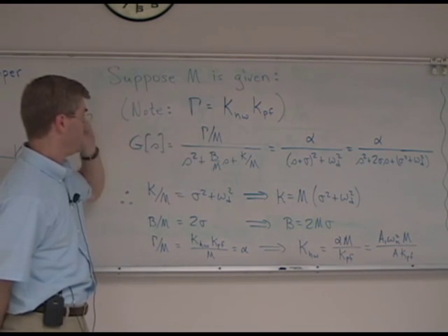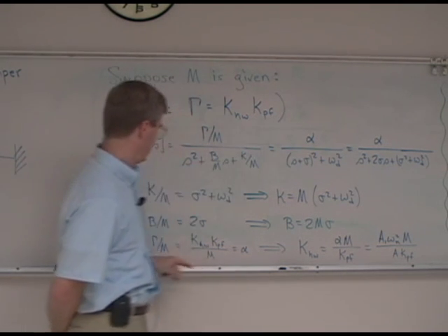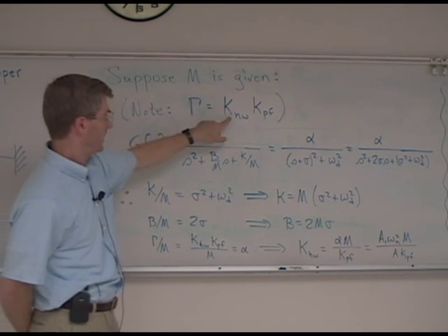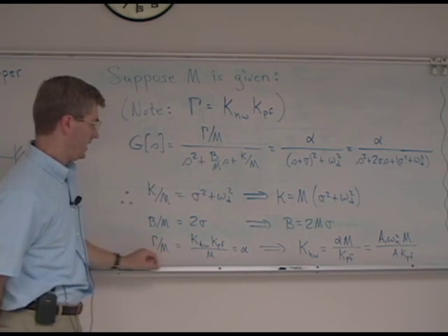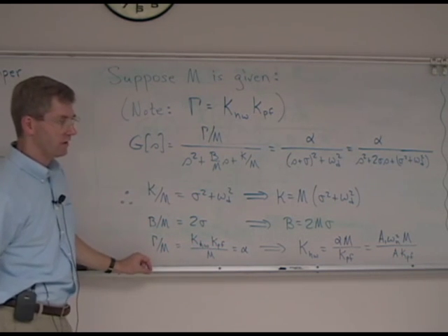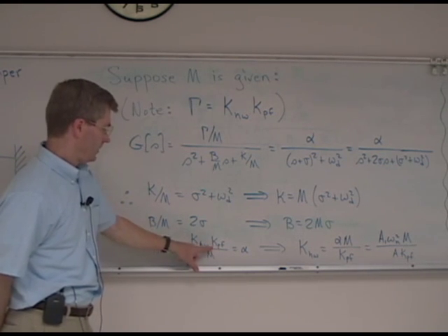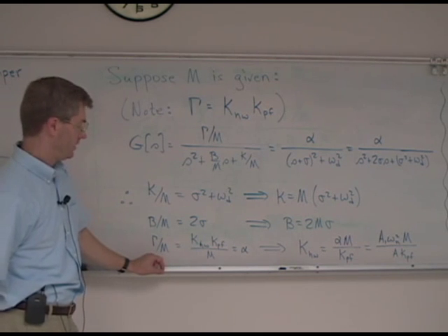Finally, we can equate numerator coefficients. Gamma over M is equal to alpha. Gamma over M, which, as we said in this first lab, is K hardware times K sub PF. K sub PF you will assign in your own lab. That might be 0.075, it might be 0.75. You need to figure out what K sub PF is that works in your system.